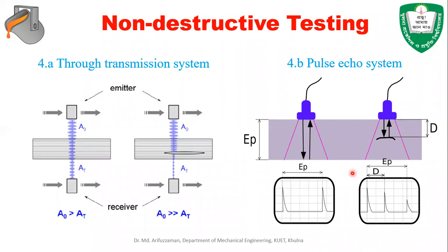Then we would assume that's the thickness. No, yep, that will be misleading. That's why you have to take the reading in at least 2, 3, 4, 5 locations to get the actual result. Okay, there might be a crack. Actually, it is a really good question. That is why, to increase the reliability, we always say you need to do at least 3 tests, and take the average.